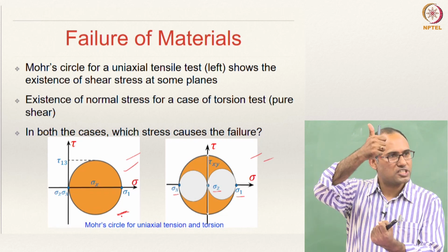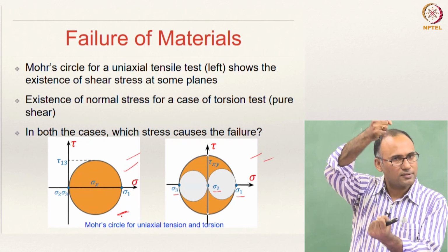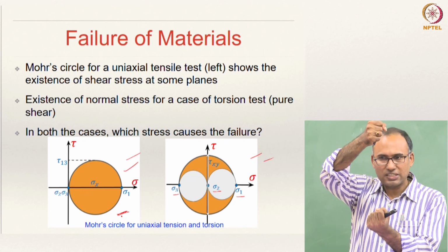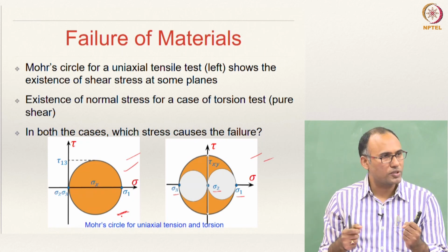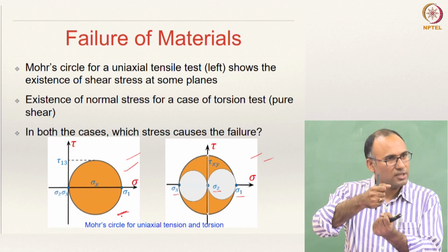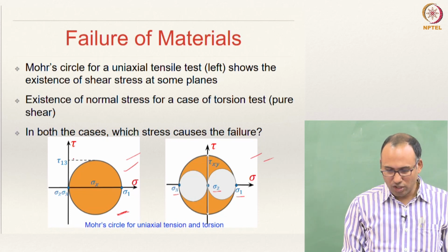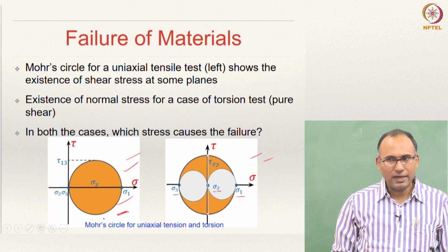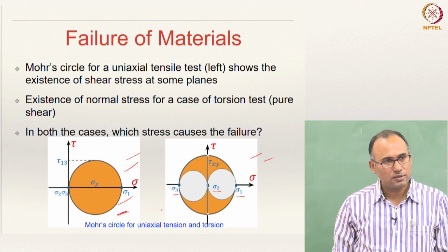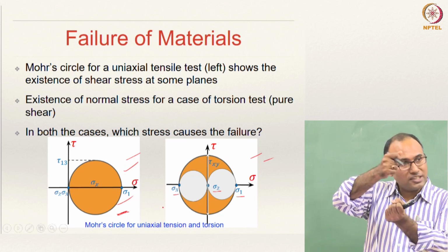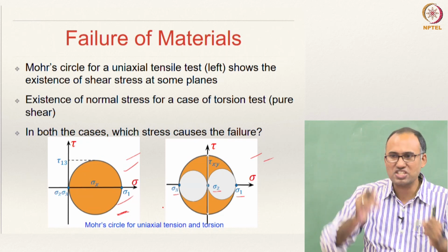So, that is your principal stress. Why is that your principal stress? Because in that plane there is no shear stress that you are applying, you are only pulling like that, isn't it. So, that is one principal stress, and the other two principal stresses will be 0 because it is a uniaxial loading scenario. And if you take that and then draw the Mohr circle, that is how it looks like, and it clearly shows you that there are planes along which, although the applied stress is uniaxial in nature, you also may have shear stress, right.